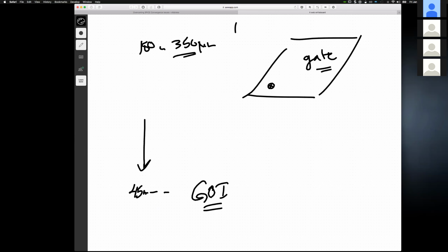But Mohammed, can I interject? This is definitely true for 45 nanometer, and I know that there are problems as soon as you get below 180. But I'm not aware of any specific maximum device size specified by XFAB for the 350 process. Yeah, so I agree with you. That's why I said the answer is yes. There are practical limits, but no specific limit. In general, thank you, Tim.